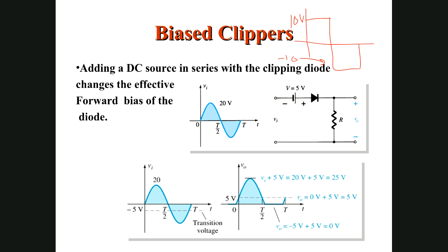In this case, your signal has got two halves. One is the positive half, one is the negative half. Let's talk about the positive half. When we use the positive half, this terminal is positive and this terminal is negative. In this case, your diode is forward biased. Why is it forward biased?